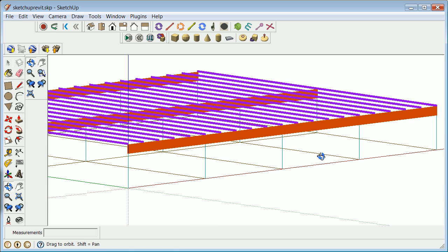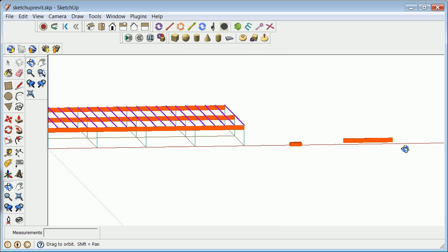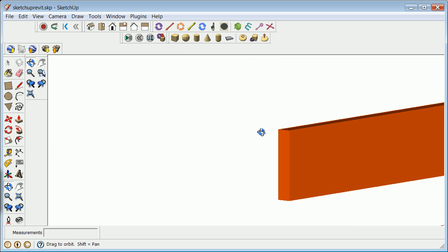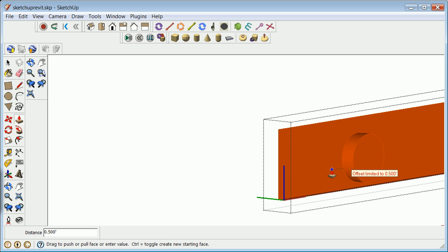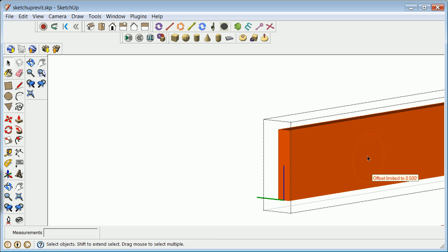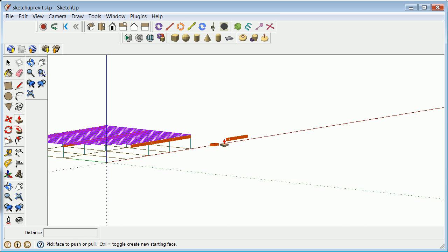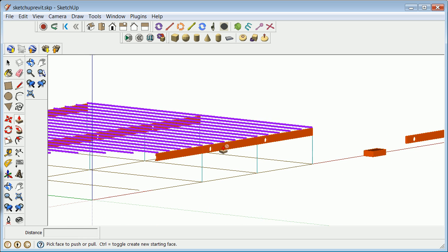So for instance, just as a last time through, if you remember the detailing aspects of this, this isn't going to work for all of them, but let's say you wanted to go inside of this and instead put some holes in here to lighten it up because it was an airframe. That would be an airframe in a building, I don't know, but maybe you had some stuff lying around. I'm just going to go ahead and push this through, and of course right-click, host component, and then each of those components would have the hole put in the same spot.